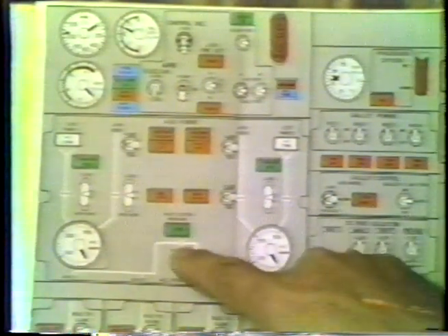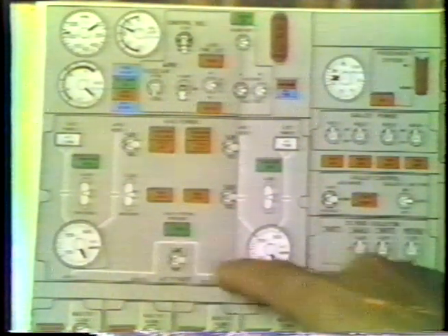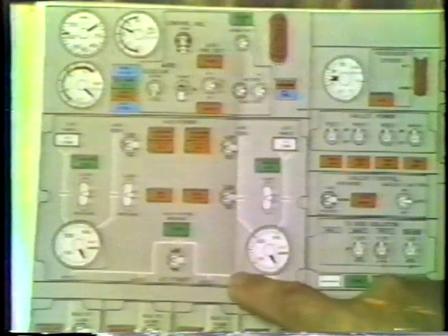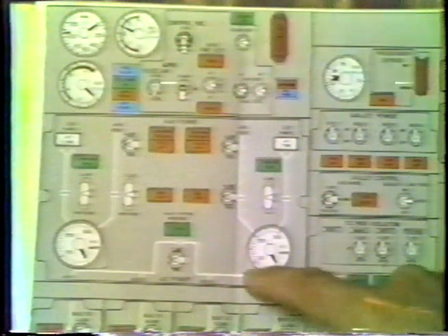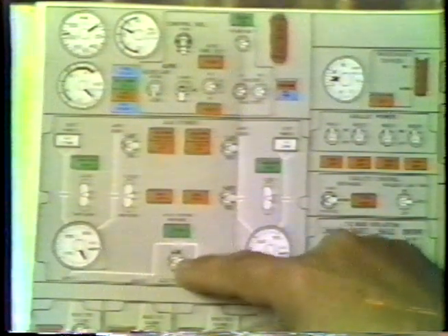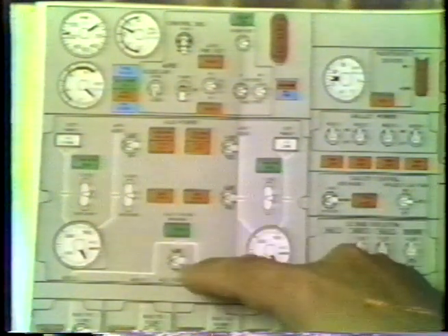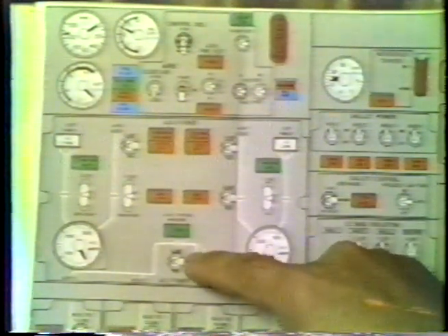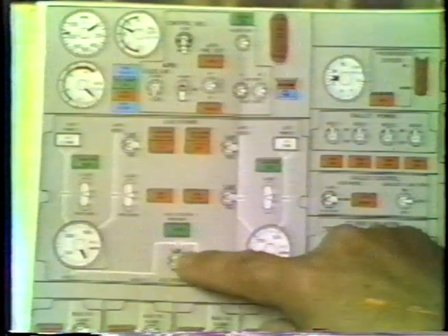The only time the split system breaker will close is when the other side of the bus has no power on at all, or you are paralleling it with other aircraft generators. The split system breaker will not close with connecting the two APU generators or ground power or any combination of it. Now, many things will make it trip, but nothing will make it automatically close.